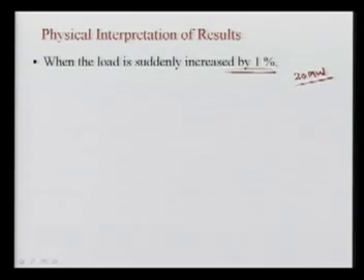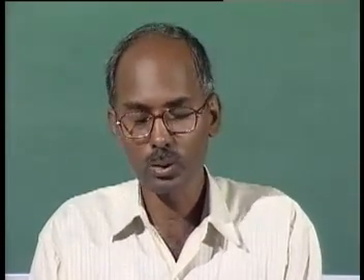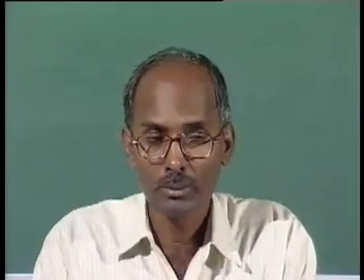First, this load is increased, meaning the load switch is closed, meaning you are going to draw more load. The governor and the net load release will not act. This load is met in a few milliseconds by the kinetic energy stored in the system. Once the kinetic energy is released, the frequency of the system will fall, and once it falls, then your governor, because the governor works on the change in frequency, will act. If the frequency is not changed, the governor will not work, because we have assumed the raise and lower commands are fixed.